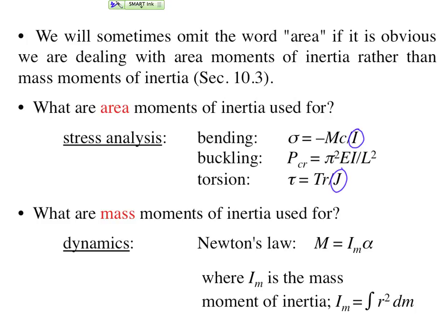The area moment also presents itself in our expression for buckling. Achieving the snap-through failure associated with buckling requires adjacent cross-sections to be vulnerable to sudden, sharp rotations with respect to one another. We can reduce the possibility of buckling by restricting our unsupported lengths L to small distances, but we can also reduce the possibility of buckling by making structural elements from stout cross-sections that resist rotation.